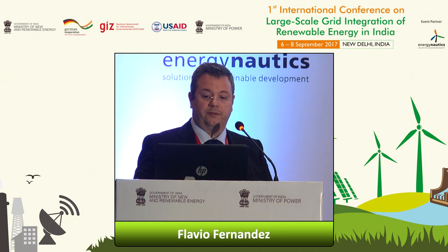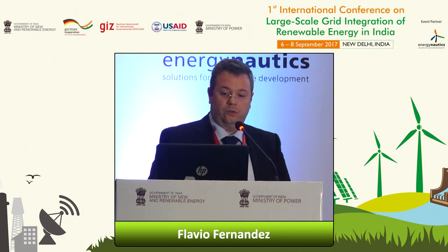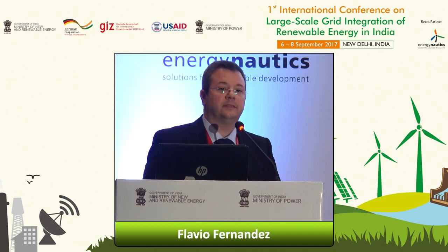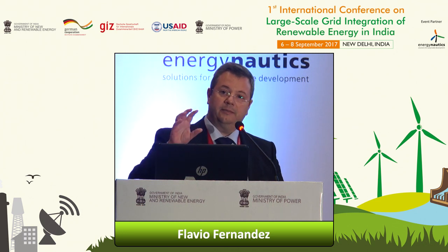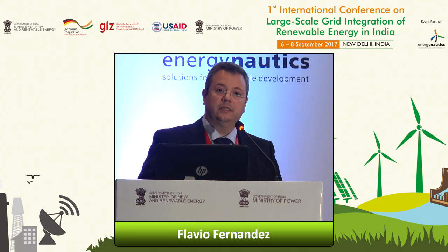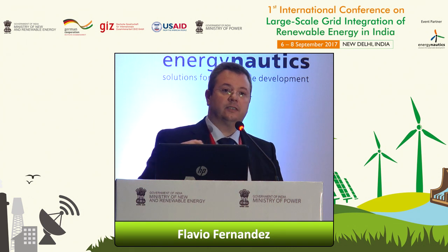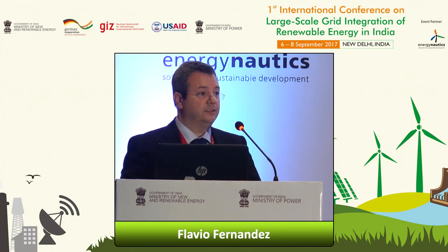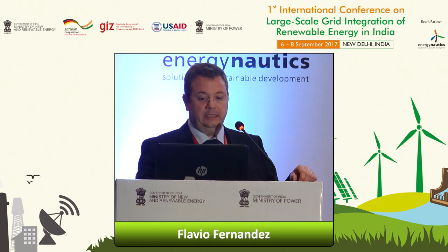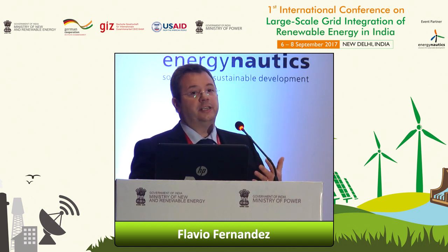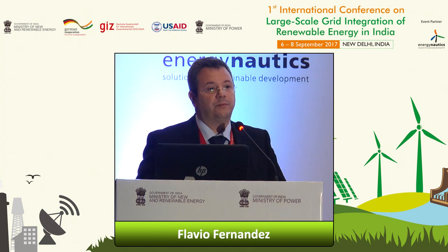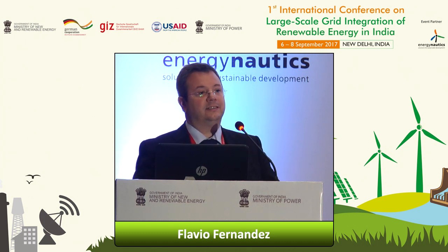You put on top of it a so-called fast control loop, a fast current controller. This will make the model behave as a current source. And on top of that, you have the external controller, which gives you the characteristic of the turbine. Maybe one thing I would like to emphasize as a message here is that there are solutions also for black box models. So it's not that you always need an open model.